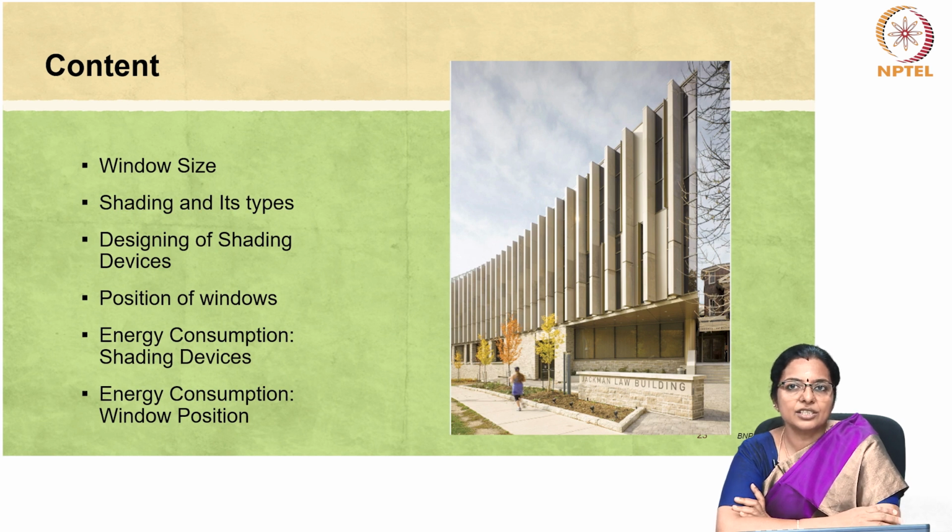So, external shading devices, whether constructed from building materials or living plants, have been shown to decrease indoor cooling loads by 30%. Further, findings suggest that shading devices are more effective at reducing cooling energy consumption compared to the utilization of high performance glazing. Even plant-based external shading solutions have demonstrated significant benefits.